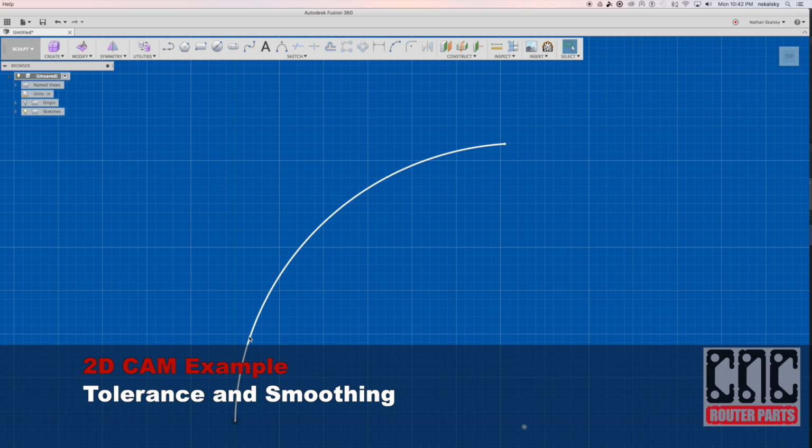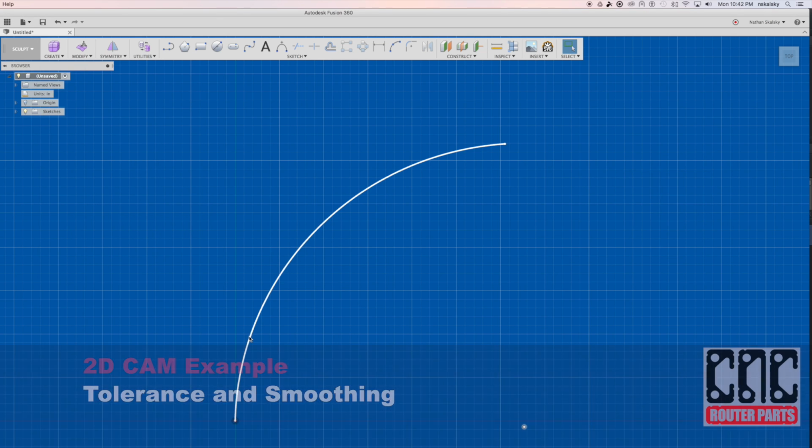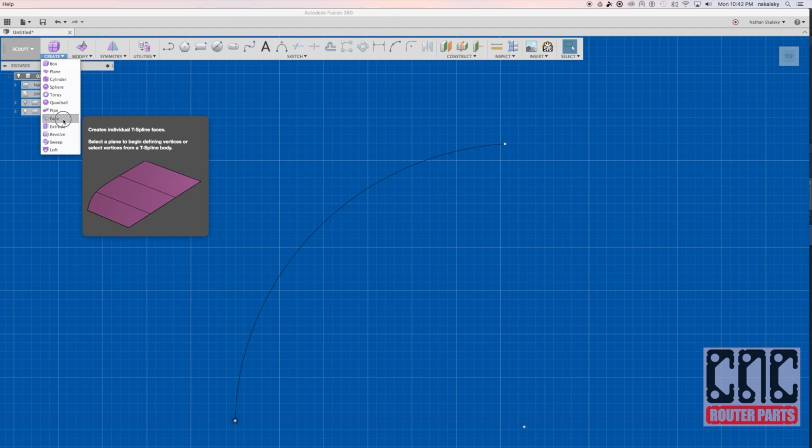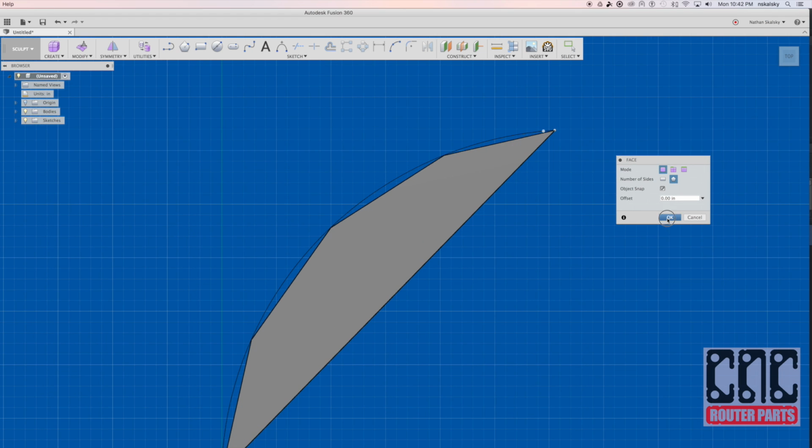With that, let's move on and talk about the considerations the CAM engine faces when deciding how to generate G-code for our design. I've created an arbitrary curve similar to what we'd find on one of the Pac-Man ghosts, and I'll use T-spline fit points to illustrate three representative scenarios and talk about the trade-offs. First, let's create a polyline with 5 data points to represent how a very loose tolerance setting would fit a series of linear movements to our ideal geometry.